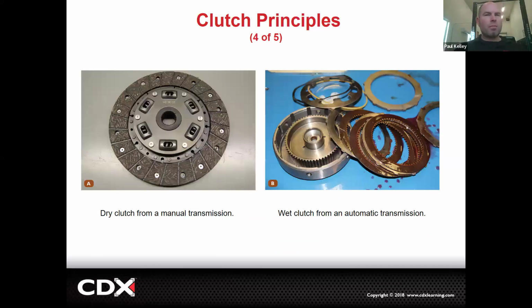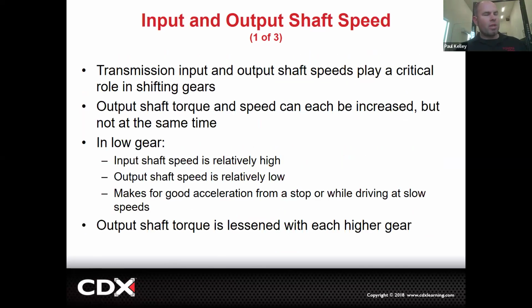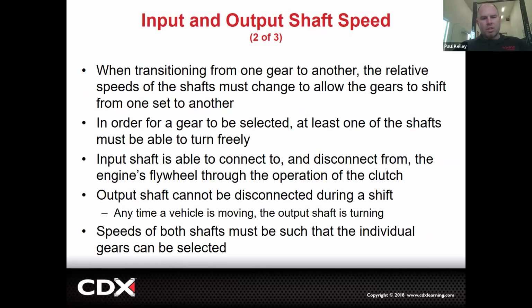Cool. So now we continue after I've been so embarrassed because of that car. Okay, so here we were talking about dry clutch, wet clutch. Just keep those in mind. And then we talked about how we could increase the torque. And then just remember, when we're driving, when we go to shift gears, we need to disconnect and reconnect. The most simple way we do that is by depressing the clutch pedal, which disengages the clutch disc, and therefore your engine is disconnected from your transmission, so you can go ahead and change gears.